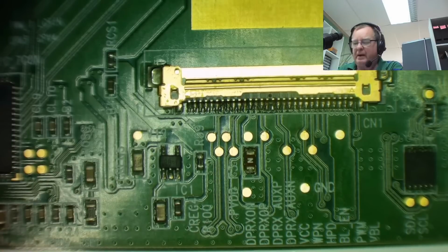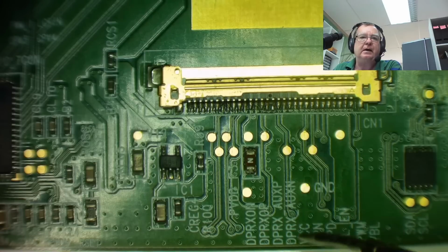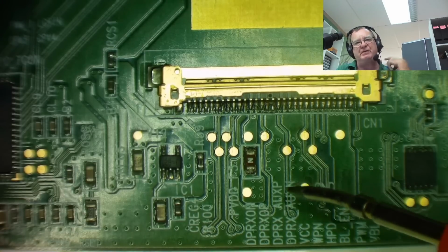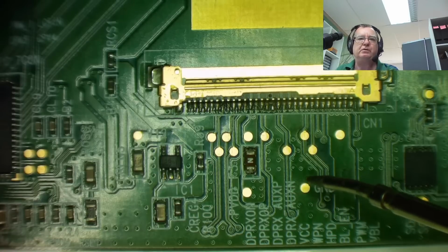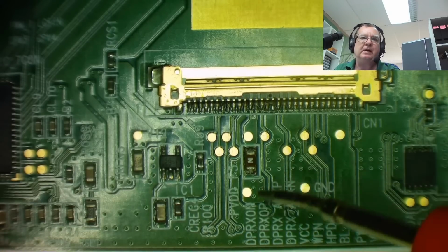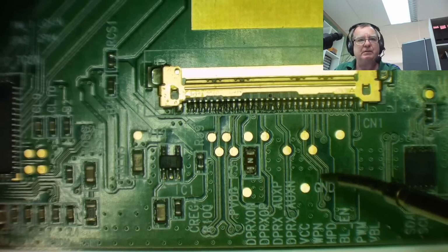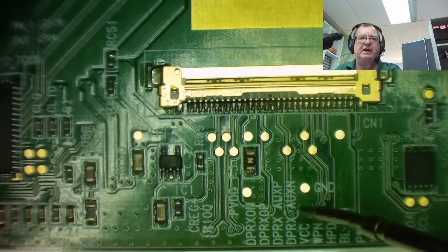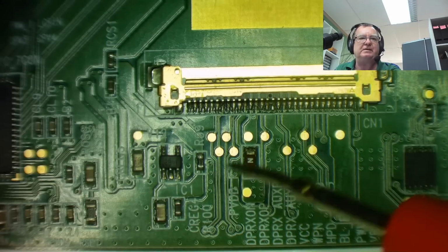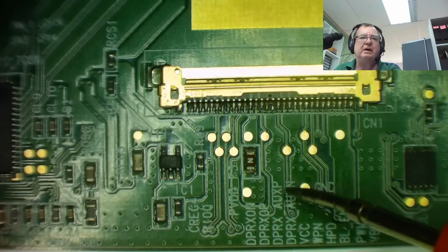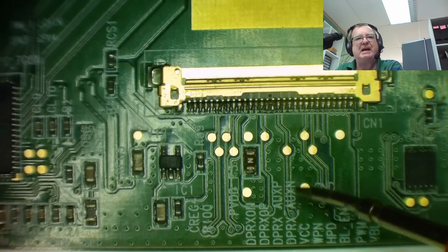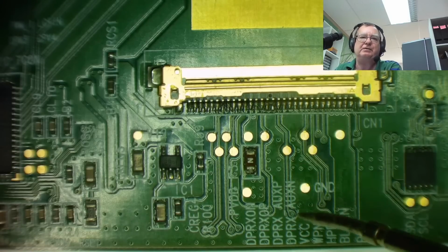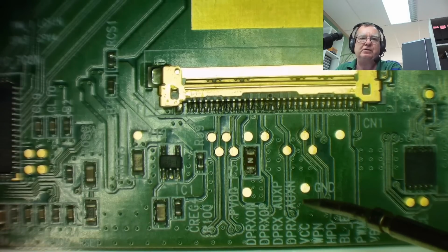He says basically the two that are marked AUX, P and N, is positive and negative, AUX plus, AUX negative. So it's a differential signal. One end goes up, another one goes down at the same time. This effectively counters interference coming down the cable. So the signal that the chip receives is the difference between these two. And if you get a spike on both, then the difference between the two will still be the same. They'll both have a spike on. That's the idea of differential signals. LVDS is actually a low voltage differential signal.